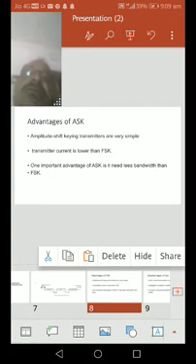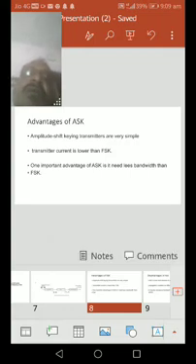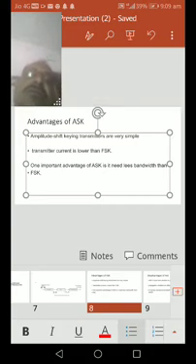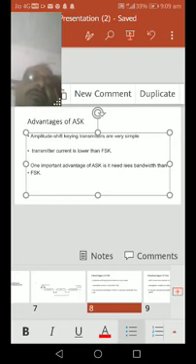The advantages of ASK modulation: first, the transmitter circuit is very simple to design. Second, the transmission power or current required is lower than FSK, frequency shift keying. Another important advantage of amplitude shift keying is that it needs less bandwidth than FSK.